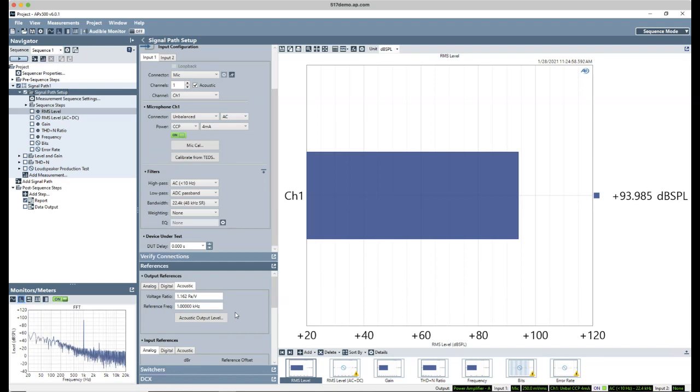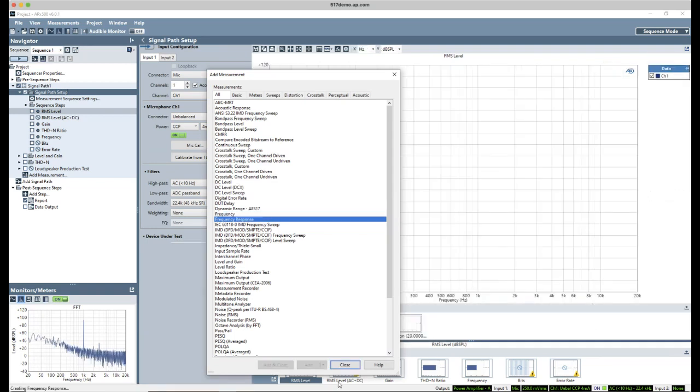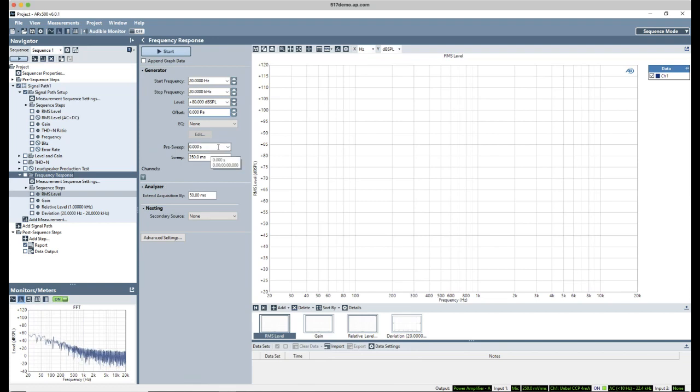The thing I'd like to do next is actually calibrate or equalize the frequency response of our source speaker. So what I'll do there is I'm going to add a measurement, and I'll just use the aptly called frequency response. And let's just start out by seeing what the full bandwidth frequency response of this speaker is. That's a good starting point. We won't be able to use it full band, but it's good to know what we're working with. So let's just do a 2.5 second sweep.